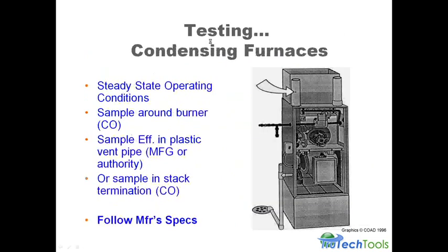On a condensing furnace, it's a positive pressure in the flue pipe. That hole has got to be sealed, okay? So typically what we want to do, if it's sidewall vented, is go outside and do the testing from the outside. Now, if you're a BPI contractor, they're probably not even allowed to test this if it goes through the roof because they don't want you drilling a hole in the flue pipe.